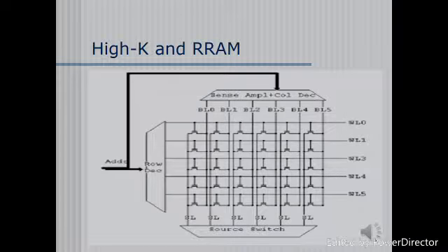Research is being heavily invested in applications of high kappa dielectrics for non-volatile memory, for example resistive RAM. The market for NAND flash memory has grown very successfully because of its density integration potential, making it easy to manufacture larger arrays of memory. Today, flash memory uses floating gate architectures. Each word line is usually made using N+ polycrystalline silicon, which goes over multiple floating gates.